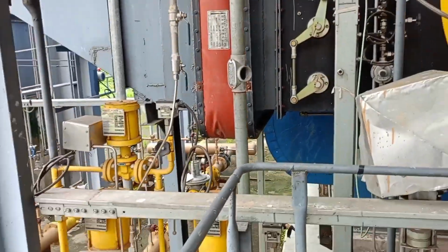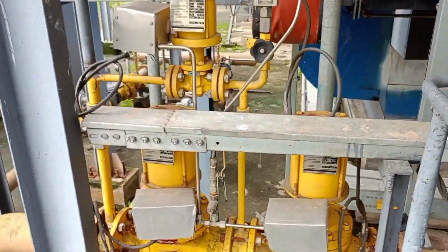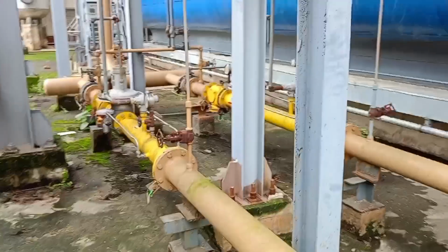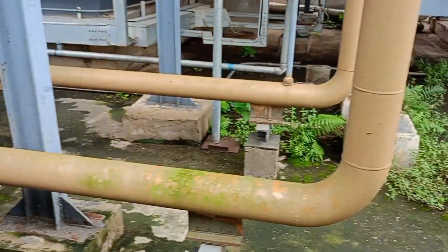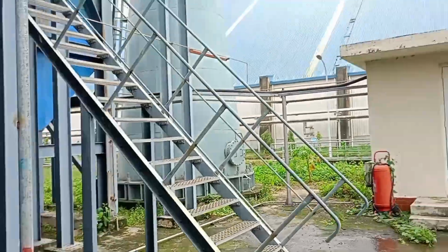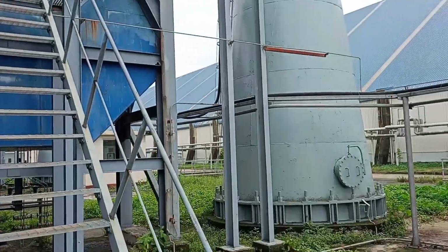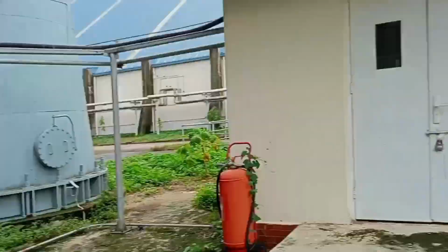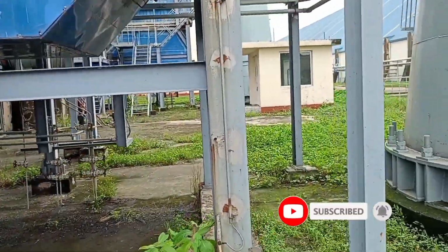And always all these parameters are maintained from the control panel. Also we can see the procedure from the burner management system, and this is our boiler chamber. Here is the boiler chamber, and here is the economizer. Here the flue gas passes through this layer to the atmosphere, and here defined gases are detected and analyzed. This is the analyzer room. Also here the drum level control and pressure control are maintained.